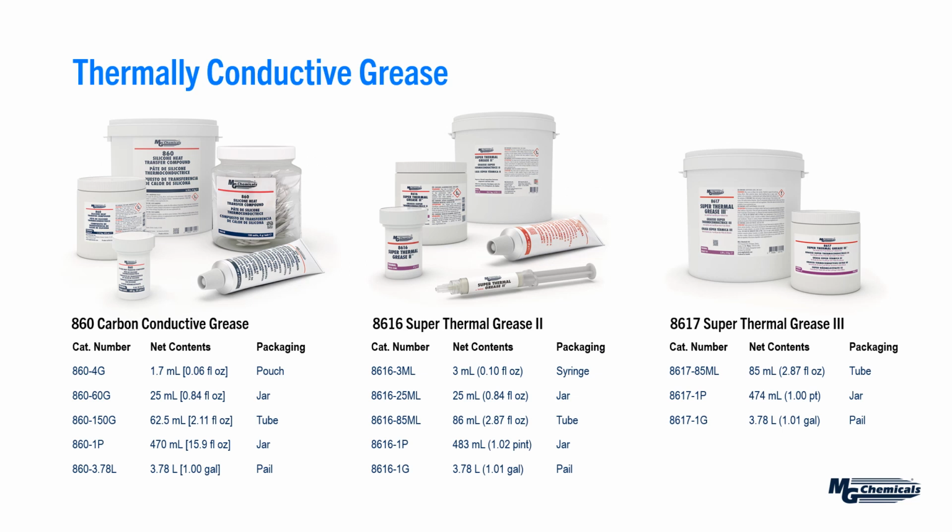Okay, and then again, several products available, sort of distinguished by their thermal conductivity values. So we have the 860, which is more of a low thermal conductivity grease. That clocks in at about 0.7 watts per meter Kelvin. The 8616 super thermal grease 2, again, is more of a high thermal conductivity grease where we're getting close to 2 watts per meter Kelvin. And then the 8617 sort of comes in the middle, at about 1, and that was designed, again, more around enhanced corrosion protection and things like that.